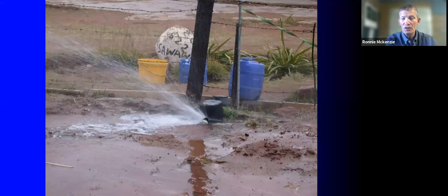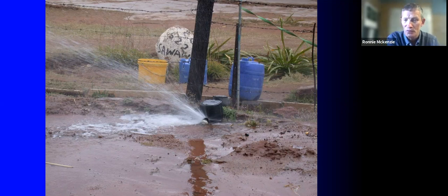Now we're on to the smaller ones. This is a burst, but it's now a connection burst, as opposed to a mains burst. These leaks tend to be a lot smaller, or they run at a much lower flow rate, obviously. A typical connection leak will run at about 1 cubic meter per hour, maybe up to 1.5 or thereabouts, at 50 meters of pressure. Obviously, if the pressure is higher or lower, it will make a difference.